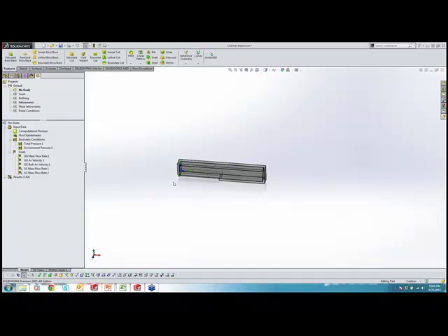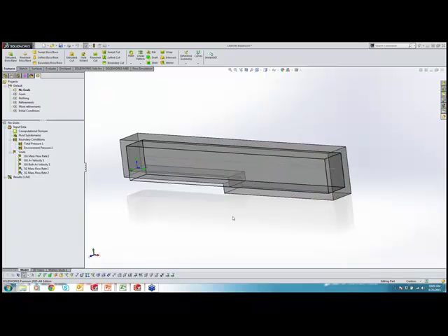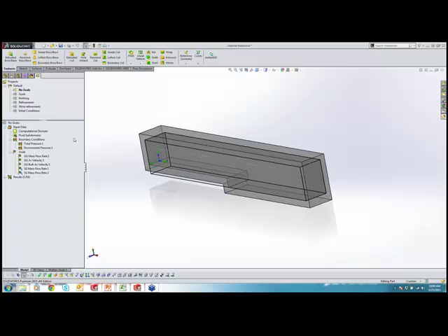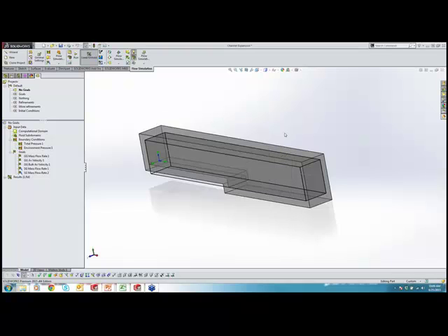There we go. So this is our actual model. If you just wanted to have a visual picture of what we're looking at here, I thought I'd show you the channel model. As you can see from our study, we have some goals here. I know it says no goals, but if you remember in my flow simulation, in calculation control options, I told it that I don't want to consider the goals. They're for information only. I'm just looking at them while the solver continues, and I'm not actually going to consider them when the solver is trying to converge.